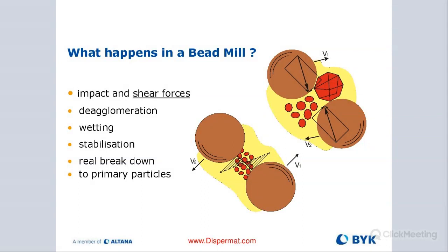So as you're milling, inside of your milling chamber, if it's a basket mill or a horizontal bead mill, these beads drift around in your slurry at very high velocities. They get pushed towards each other and then they drift away from each other at really high velocities. That drifting action is actually what's producing the shear.